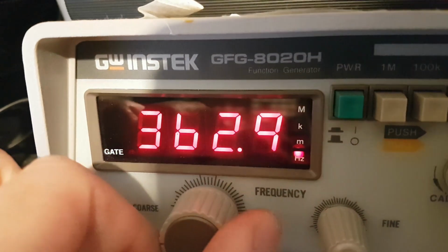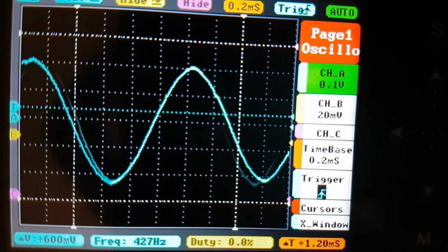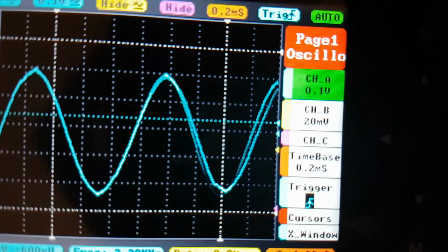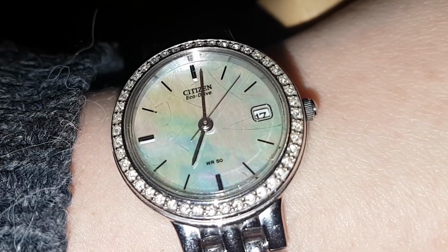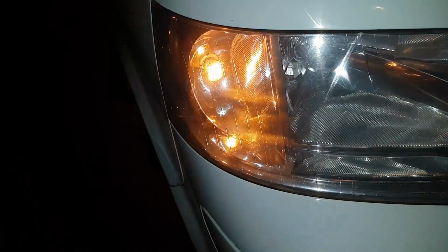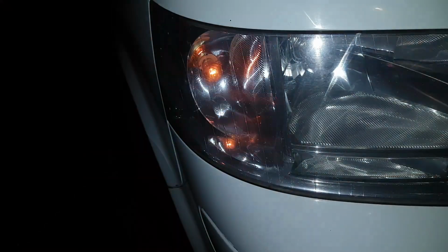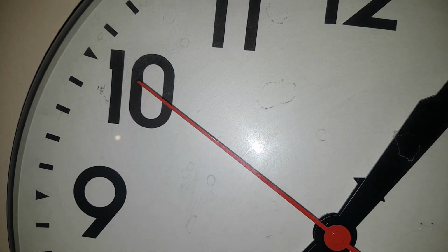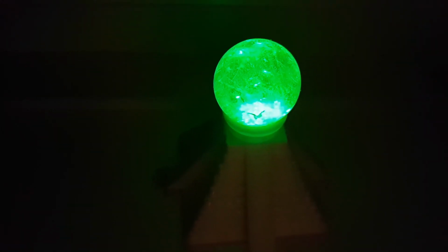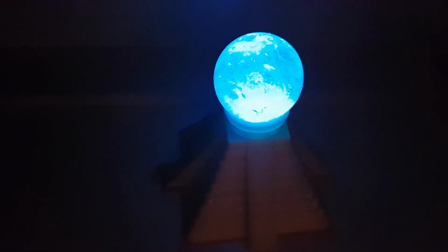So what is an oscillator? Well, an oscillator is a general system or circuit that changes an output state. Here we have a signal generator which gives us an output sine wave, and we can change that frequency. We sometimes want a stable frequency for timing and flashing circuits such as these indicators here. And we're still going to be using some sort of oscillator even in an advanced timing system. We might have a flashing light like the security light, or possibly an RGB light, like these hippie RGB color changing systems here.